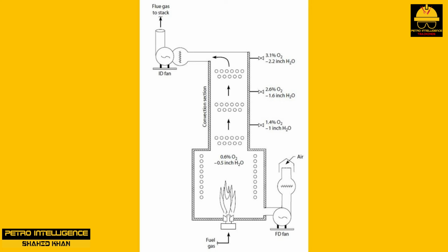This boiler is puffing, too. Perhaps I should have shown its convective section walls alternately convex and concave, but instead I have just entitled it the puffing boiler. Here is what actually causes the puffing, vibrating, or thumping. The fuel gas is not properly combusted at the burners, so partially combusted hydrocarbons and perhaps some totally unburned fuel pass up into the convective section with the flue gas.